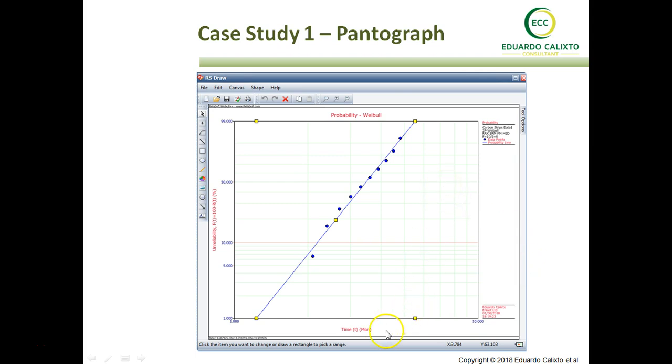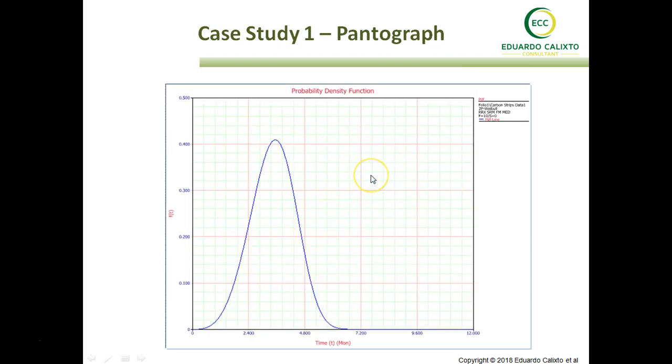So here we can see the plot based on the Weibull paper that is calculated based on the ranking method. So if we've got 63% here, we've got the eta value, and of course the angular value here. If you look on the paper, you get the beta value. It's another method that we can apply, just to demonstrate that in this software we can also carry out this analysis.